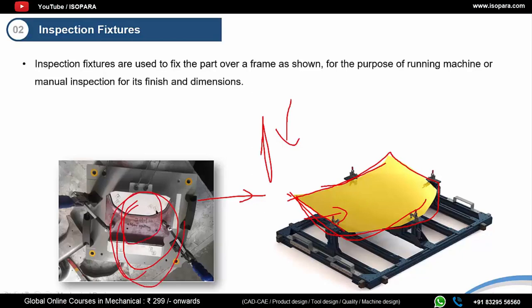This sheet comes in the form of a big, giant, heavy roll of stainless steel or steel, and it is just unrolled and fed into this stamping machine, and it will keep on producing n number of products. So this is what mass production is basically. One product after the other, all these hood components are coming out, but you need proper tolerance and accuracy.